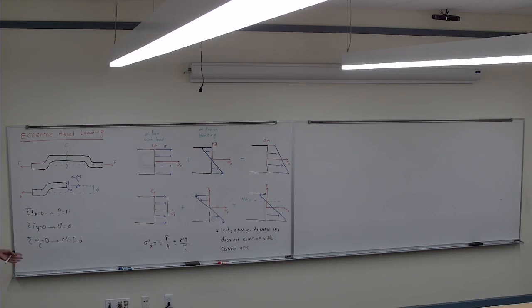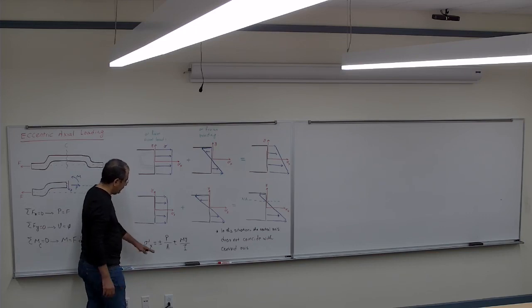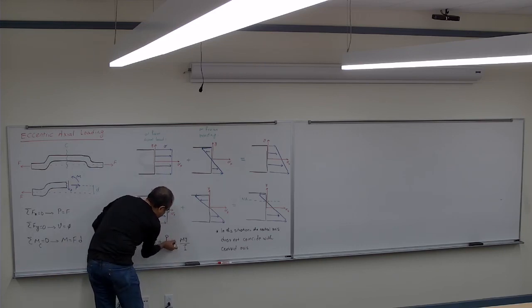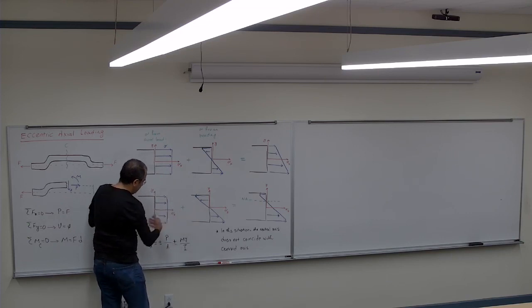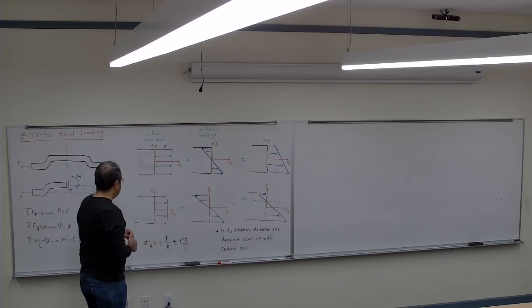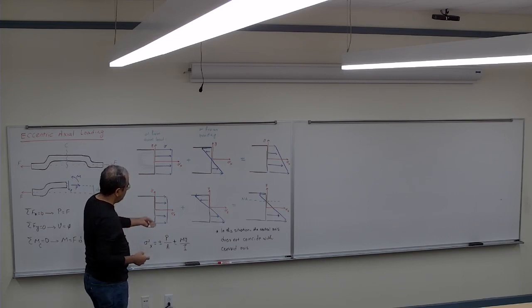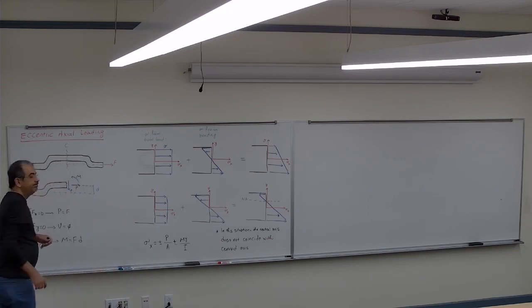So 2 points again. If you want to calculate tension, you have to find the tension from the axial force, you have to find the tension from the bending, and then you have to choose the sign, or you draw it so you know the sign. Any place that they have the same sign, you add them together. Any place that they have opposite signs, you subtract them. So that's going to be your end result. And then the neutral axis again doesn't pass through the center. Any question?